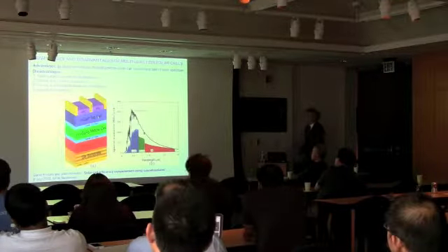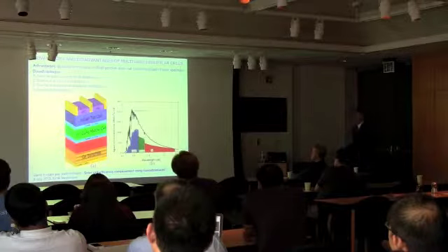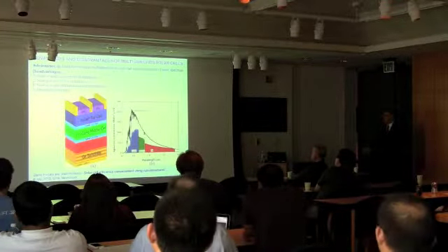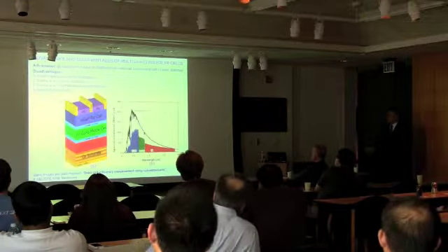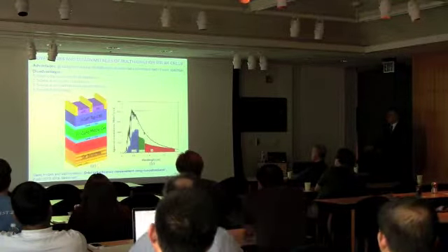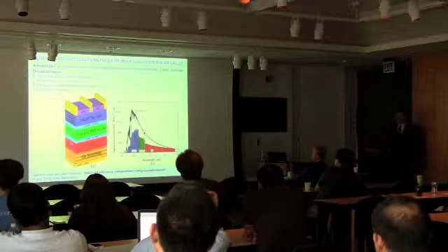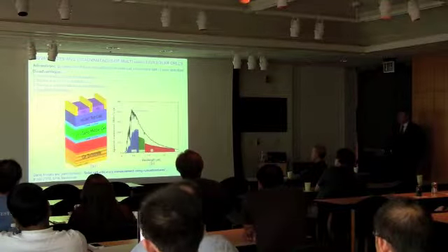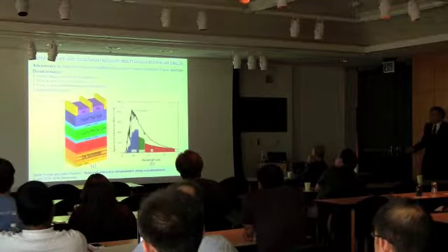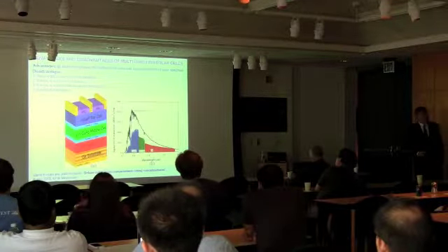Here, for example, is shown gallium phosphide. This solar cell absorbs this part of the spectrum, and as you see, it's shown what can be transferred into useful power. This part is lost. Next will be a material with a narrower band gap, gallium arsenide. Adding it below, I win a little bit because I reduce the so-called thermalization losses.